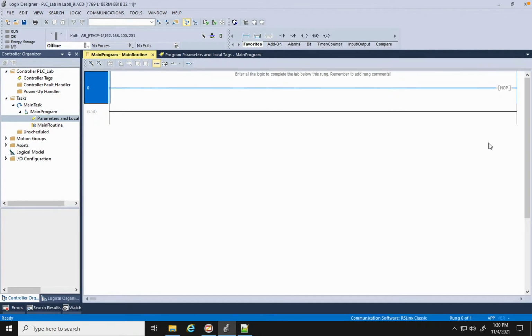So the first thing that we can realize is that we've got a single transition button that's going to cause us to transition between each of the states. And it said that we would need to use the rising edge, which makes sense, right? You don't want someone holding the button down and the states continuing to cycle. So if you're in state 1 and someone presses and holds the button, you should move to state 2. You shouldn't then also move to state 3, 4, and then back to 1. So we will need to do rising edge detection on our transition button,